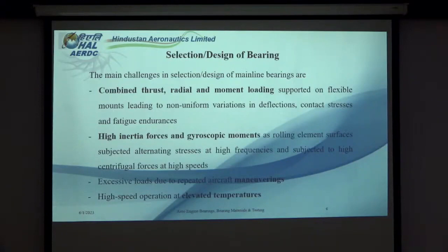In an aero gas turbine engine, the mainline bearings have to undergo combined thrust, radial, and moment loading, supported in flexible mounts, leading to non-uniform variation in deflections, contact stresses, and fatigue endurances.